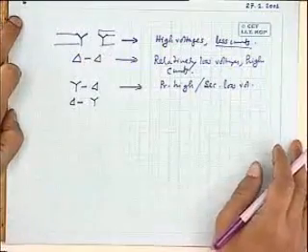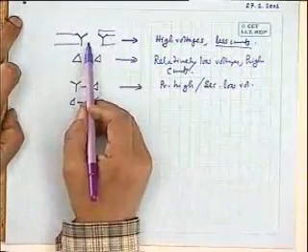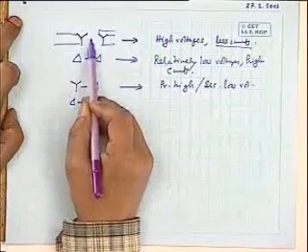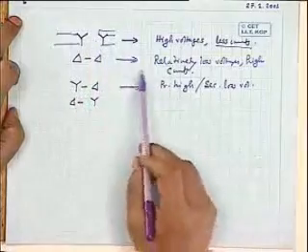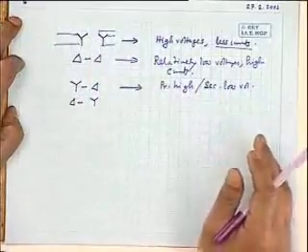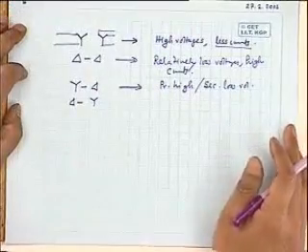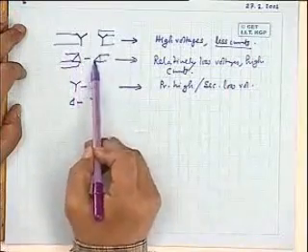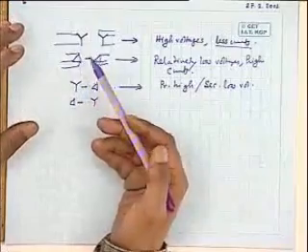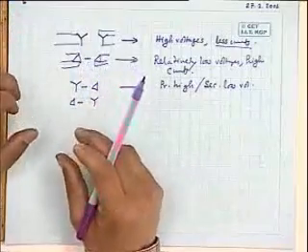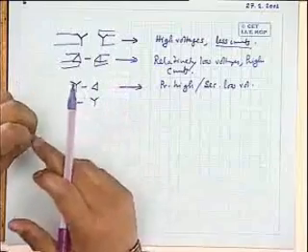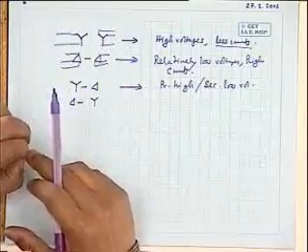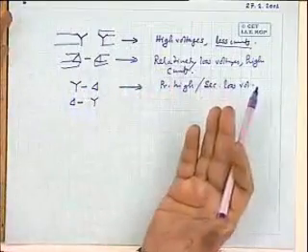Of which, of course, the star-star connections may give you some problems, unless it is provided with a stabilizing delta connected additional winding on this transformer. Delta connected transformer has got its own advantages. Tell me something. One thing is clear, the third harmonic business we need not bother about, because third harmonic voltages induced in the winding will try, in a self way, to make the flux more or less sinusoidal. So that problem will not be there.